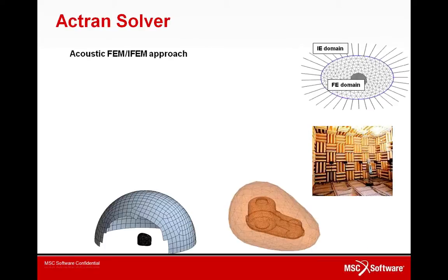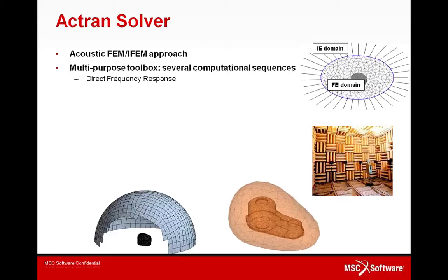So Actran is based on the finite element method that is complemented by infinite elements to account for the radiation in free field. Actran can really be seen as a multiple tool toolbox, and different computational sequences are available to solve your acoustic problem. First, there is a direct frequency response that is the most popular sequence. The solution is computed in the so-called physical space, and the model can include any kind of complexity or damping mechanism.